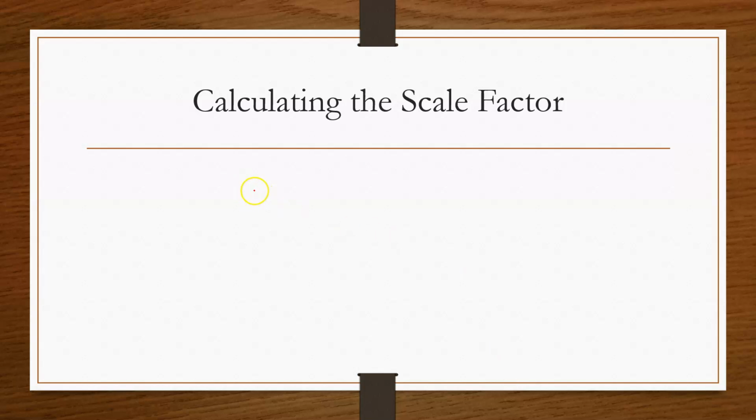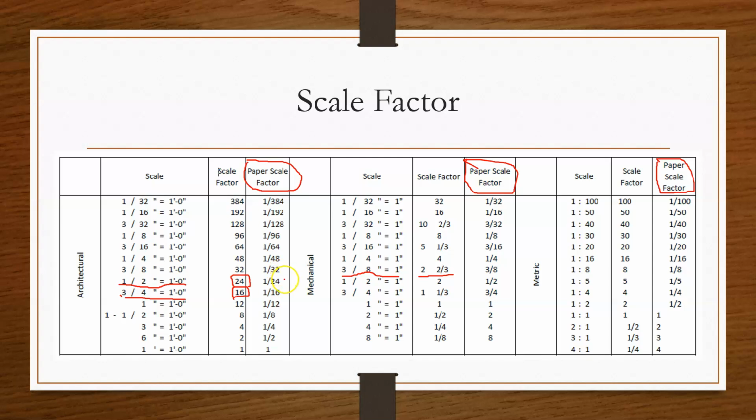Mainly because if I have a number that's sitting at 1:20, just treat these two colons as an equal sign, and it makes it a lot easier for you, right? So we're back to the same thing that we did before. Remember that if I got a 1 on this side, that's my goal. Or if I divide this 1 by this 20, scale factor is simply 20. Okay? Super duper easy to do when we're dealing with the metric scale, and that's what you're seeing here.